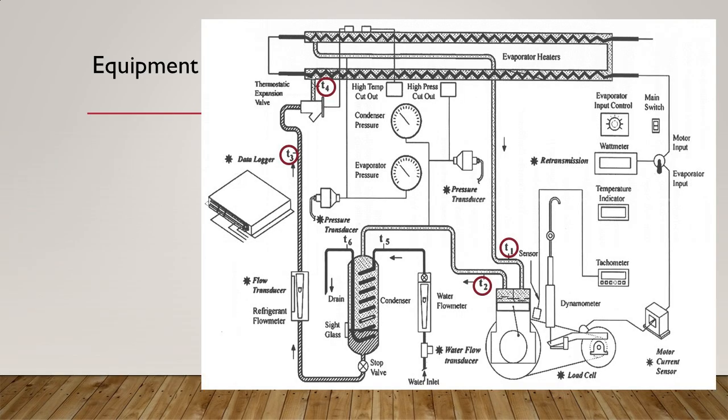Input heat load to the evaporator is generated artificially by electric heating elements at the evaporator, under the control of a variable transformer. The refrigeration unit is equipped with the necessary instruments and devices for measuring flow rate, pressure, and temperature of refrigerant and cooling water at various locations, a dynamometer for measurement of motor torque output, and a built-in tachometer to measure rotational speed of the compressor.